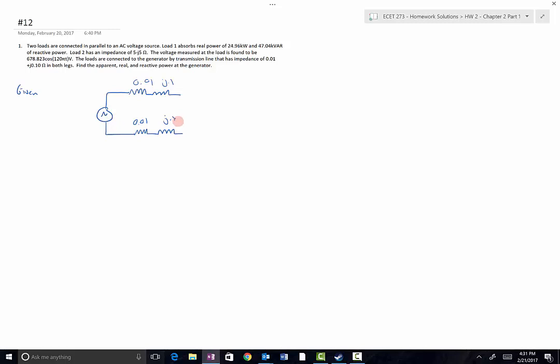So I think it makes sense to divide it up like that, because the wire connecting the generator to the loads that we'll draw over here has an impedance associated with it. So does the wire that closes the circuit. If you were just modeling the wire by itself, that's a pretty good way to represent it. It's not how it's usually done though. Usually you just lump it all together up here because the result is the same for the circuit.